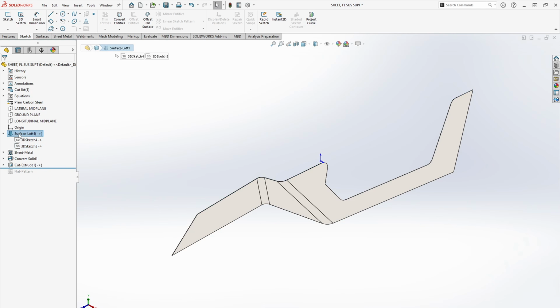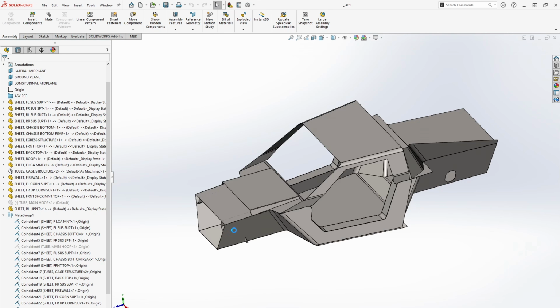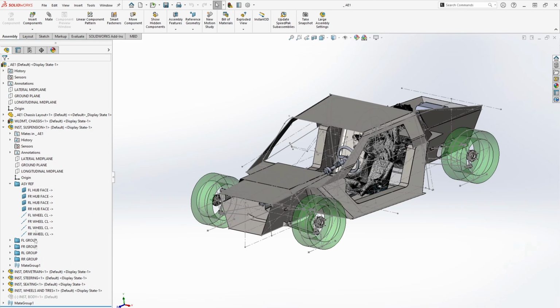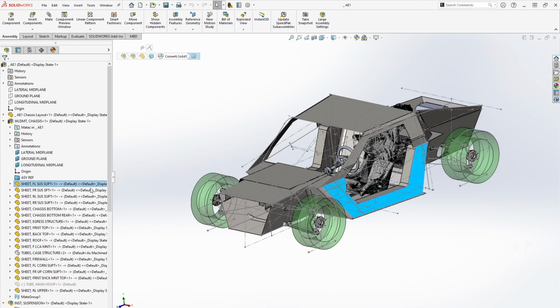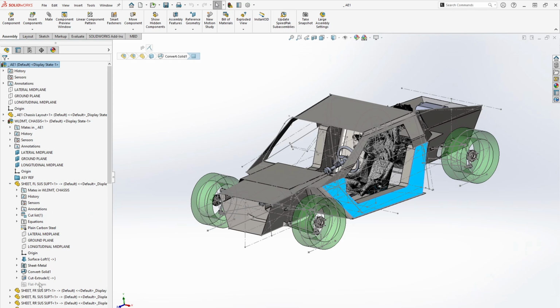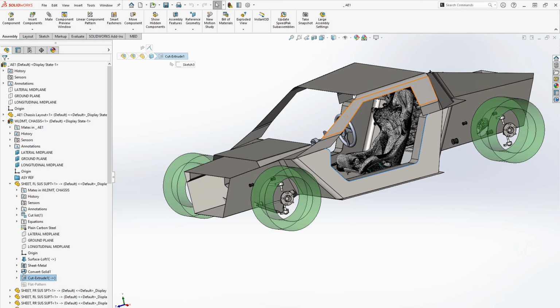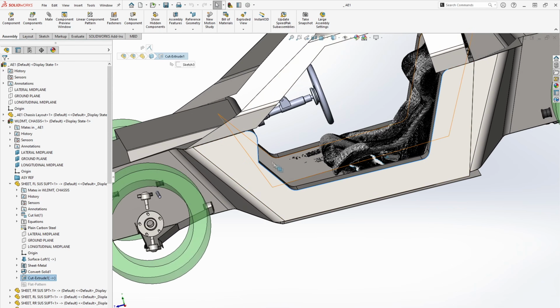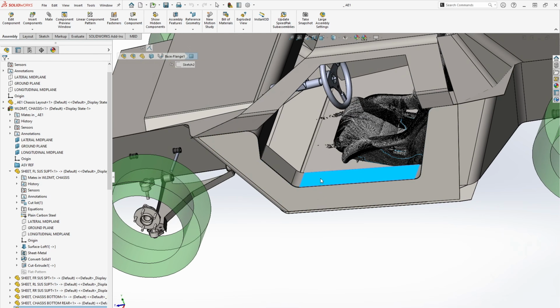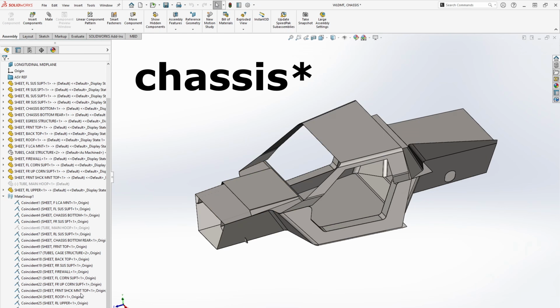Then I convert it to a loft. From a loft, I convert it to sheet metal. Back in the main assembly, I've got my newly formed sheet metal part, and let's say I need to make a cut in the side of it. Well, I do just that. At that layer, let me hide this sketch so we can see a little bit better, I will create this sketch that's based on this piece part that will now cut a hole in this piece of sheet metal. That's how the majority of these suspension components are drawn.